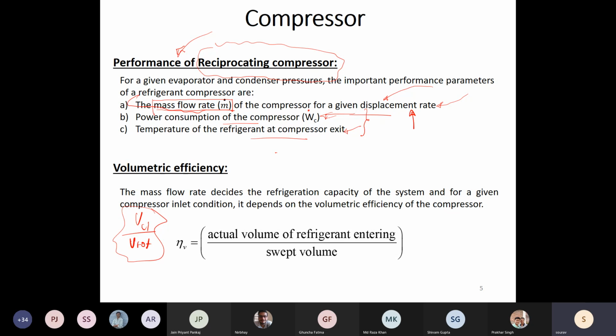Is volumetric efficiency a fixed number? The amount of air and fuel mixture entering depends on the pressure difference, so all the air cannot enter. The actual air divided by the theoretical amount is the volumetric efficiency. Yes, great. So that is not a fixed number, as you said. It depends on the operating condition, so it depends on the pressure ratios. Okay, so the same is the case with a reciprocating compressor.